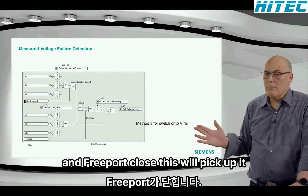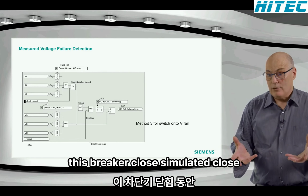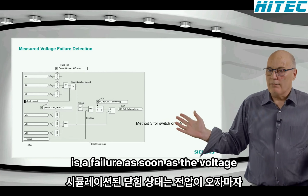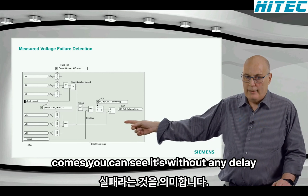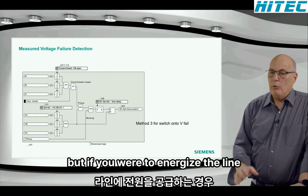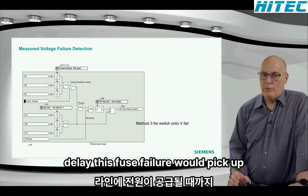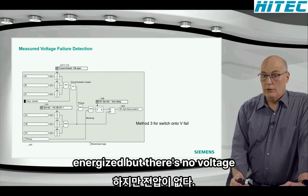Okay, so at the bottom you see no voltage and 3 pole closed. This will pick up. It doesn't matter. It just means that during this breaker close, simulated closed condition with no voltage connected, the relay would indicate there's a failure. As soon as the voltage comes, you can see it's without any delay. As soon as there's a voltage present, it will reset the bottom input. But if you were to energize the line without voltage, then after the set time delay, this fuse failure would pick up and tell you, look, the line has been energized, but there's no voltage.